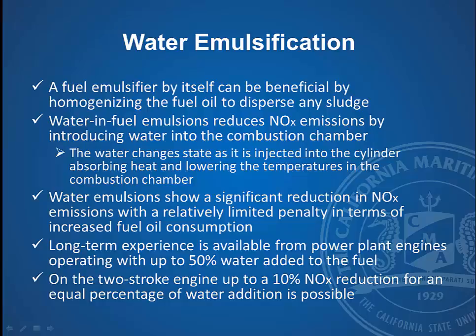But what we're doing now is water and fuel emulsions, which reduce NOx emissions by introducing water into the combustion chamber. You can mix as much as 50% water in, and that water, when it enters the combustion chamber after being injected, will flash into a gas from the heat, and it will absorb heat as it flashes. That will lower the temperature in the combustion chamber. Water emulsions show a significant reduction in NOx emissions with a relatively limited penalty in terms of increased fuel consumption, and they can reduce NOx by as much as somewhere around 70%.